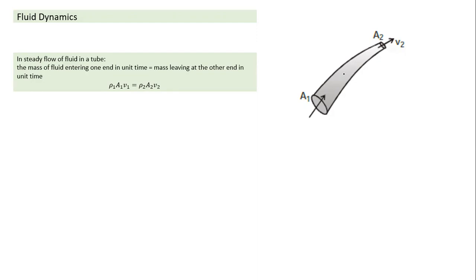So just by the fact that the volume within the two cross sections remains constant and density remains constant, it gives this condition: mass flow rate entering through the cross section here has to be equal to mass flow rate out. So we have done volume flow rate is area of cross section into velocity. Mass flow rate is density into area of cross section into velocity. So these two values must be equal in a steady state.